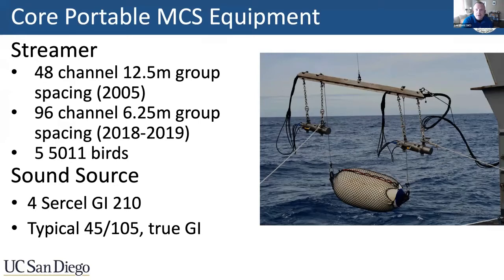It was silicone oil filled. And so in the past several years, we've been recapitalizing it. I've been writing proposals to recapitalize that. Now we've got a 96-channel, and we have a few spare sections. We're trying to acquire spare sections wherever I can. And the 96-channel went to 6.25 meter group spacing, so I could take advantage of higher frequency, higher resolution projects.